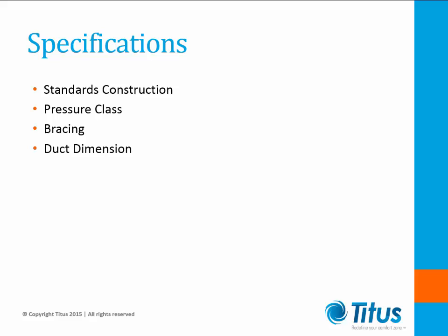Leakage rates for the ductwork should be identified in the specifications. You should also call for job site testing and verification. Inside ASHRAE Chapter 21, they currently suggest a maximum of 5%.